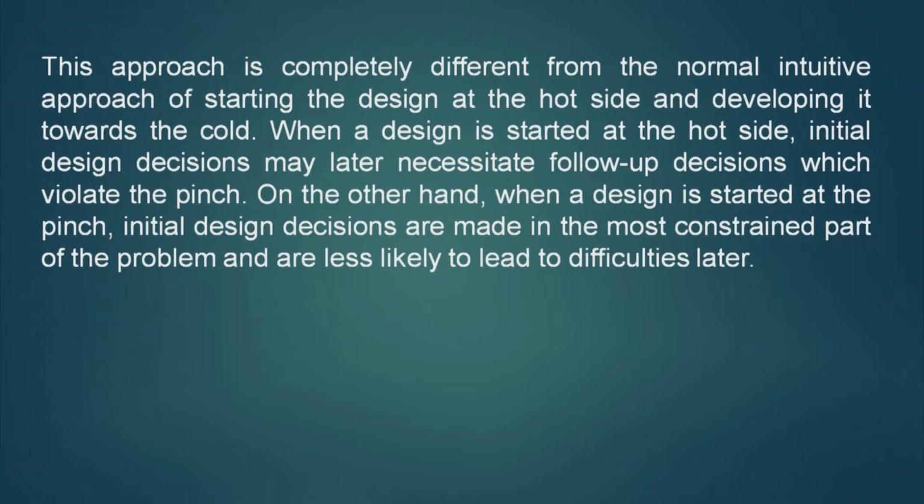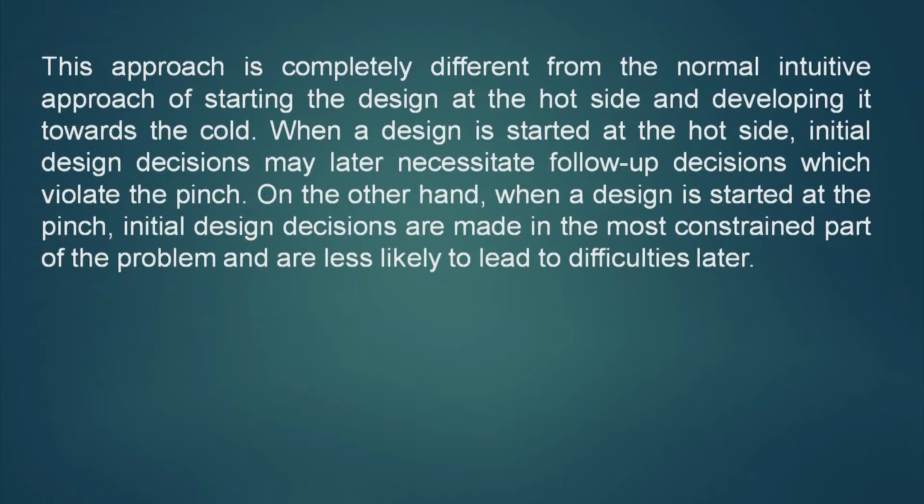Now, the approach of pinch design is totally different from the normal intuitive approach. The normal intuitive approach starts the design at the hot end, developing towards the cool side. When a design is started at the hot side, initial design decisions may later necessitate follow-up decisions which violate the pinch.